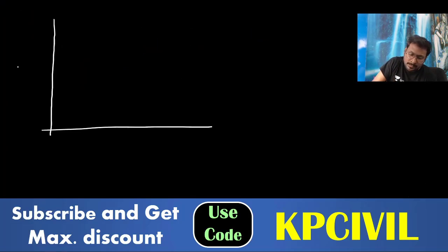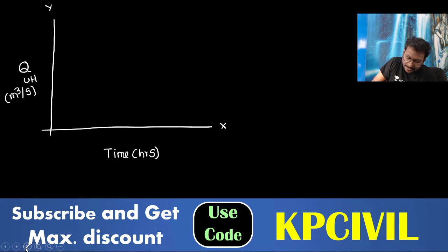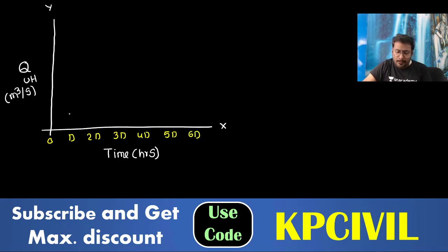I will show you. So again we are plotting QUH in meter cube per second, unit hydrograph discharges on the y-axis, and time in hours on the x-axis. I am writing time in terms of D ordinates: 0D, 2D, 3D, 4D, 5D, 6D like that. Now, first I plot the first 1 centimeter D hour rainfall like this, the unit hydrograph of storm 1.